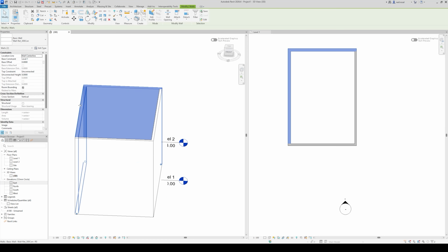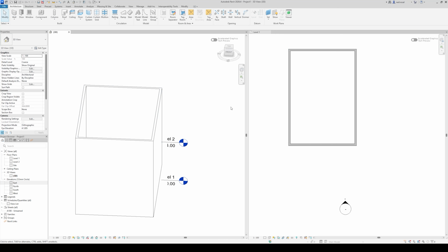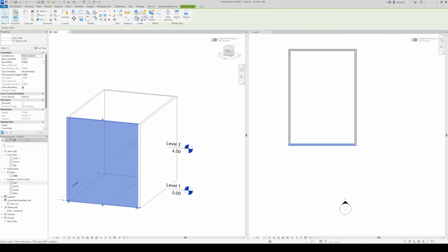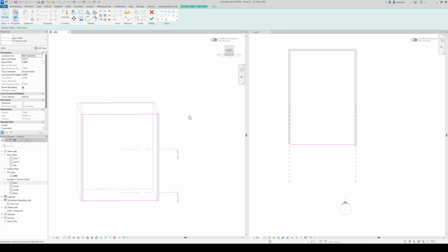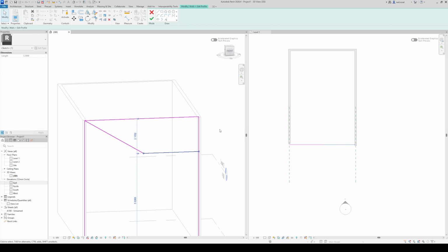To select multiple walls, you want to hold Control Shift and then left click, not just walls itself, but other elements within your project. Yeah, I'm going to change it over here. So everything's 8 inches. If I want a weird wall, let's say, I can edit the profile on my wall. Let's say I want a slant in my wall. I'm just playing with these commands to show you Revit stuff. So I want this slant, this wall opening.